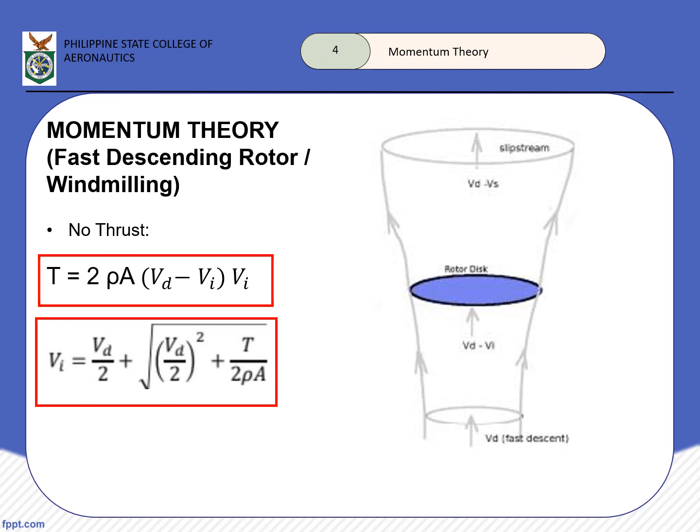I just did not edit it properly. But the two equations: the capture area is still below, but the rotor is absorbing momentum from the stream and a divergent slipstream appears above. As you may see there, our slipstream is now above. So, this negative change in momentum will again produce a thrust, or a vertical drag. So, this flow state can be used for auto-rotation of our blades.